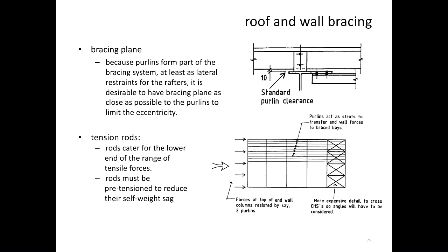roof level. So what happens is that bracing usually gets tied to the beam or the rafter, okay? That bracing will have a cleat that comes off from the rafter, and that cleat is where the roof bracing is tied to.